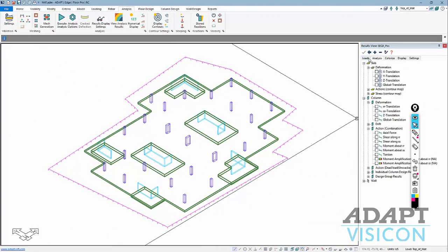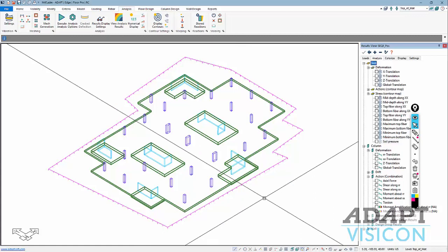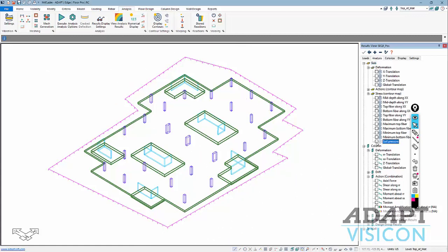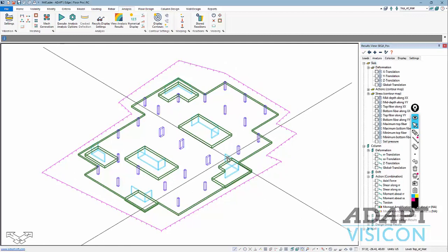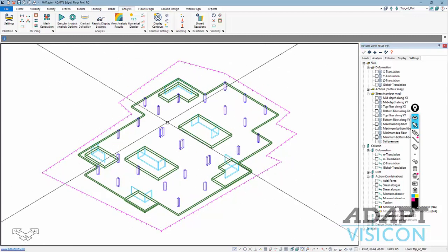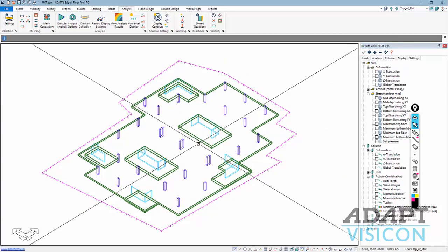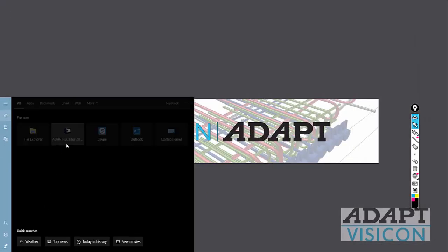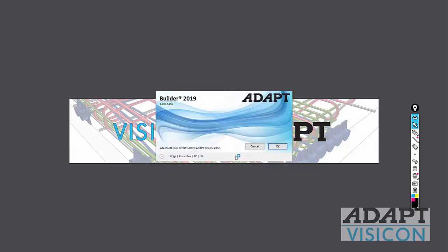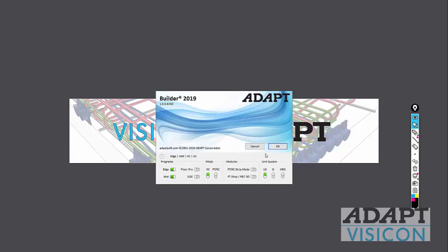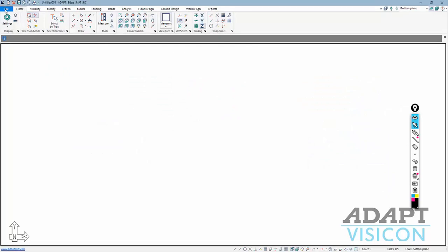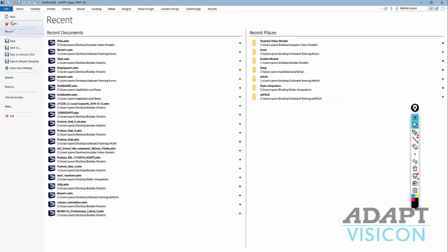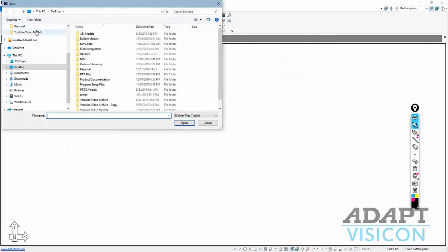and if we go over to slab, let's say stresses, and look at the soil pressure, you'll notice that this does not allow me to check soil pressure in this instance because we're in Floor Pro. If we transition into mat, we can check the soil pressure here. So I'll just save the model, close out of this. I'm going to reopen the program, and I'll transfer this over to mat, and I can recall the same model and solution. I'll go ahead and open up that file.